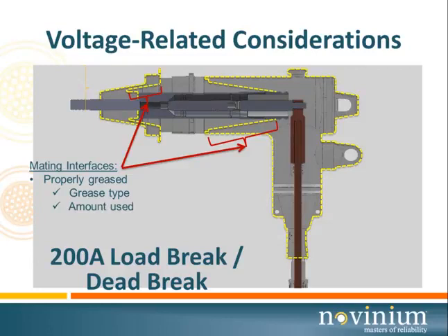The amount of grease. We've got the right grease. Can we over-grease it? Yes. This interface, if you put too much grease on here, well, there's only a very small reservoir down here at the bottom. If you put too much on, you're not going to be able to get this insert on proper. It takes a lot of extra grease, but if you put too much on here, you're going to get it down in this area. You're not going to get the elbow seated properly.